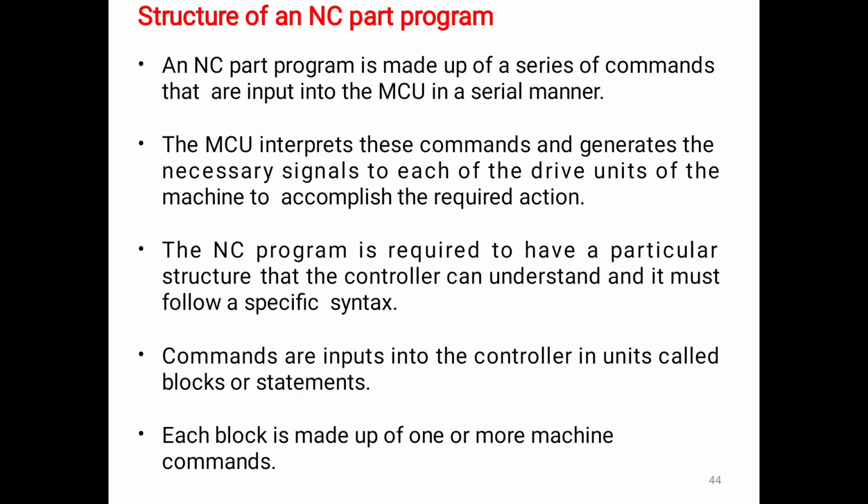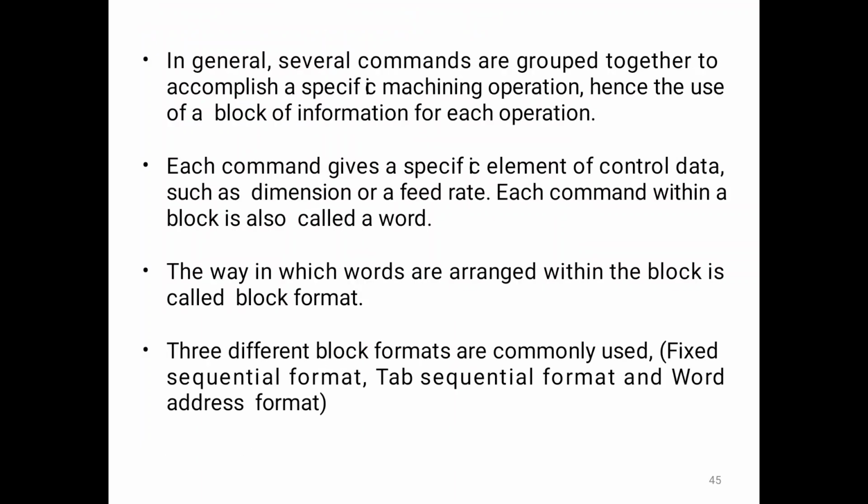The NC program is required to follow a particular structure that the controller can understand, and it must follow a specific syntax. The commands are input into the controller in units called blocks or statements. Each block is made up of one or more machine commands. In general, several commands are grouped together to accomplish a specific machining operation. Hence, the use of a block of information for each operation.